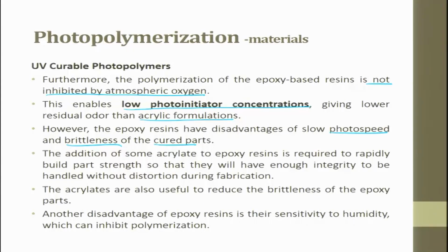The addition of some acrylate to epoxy resin is required to rapidly build part strength so that they will have enough integrity to be handled without distorting during fabrication. The acrylates are also useful to reduce the brittleness.